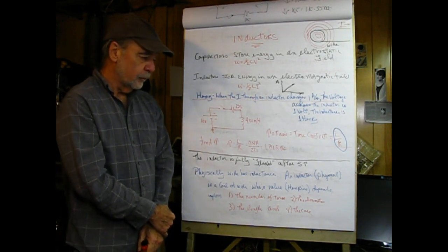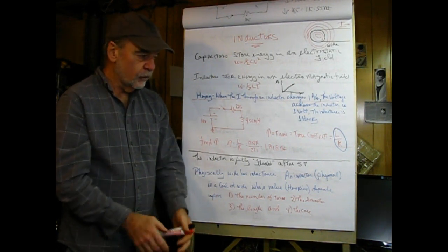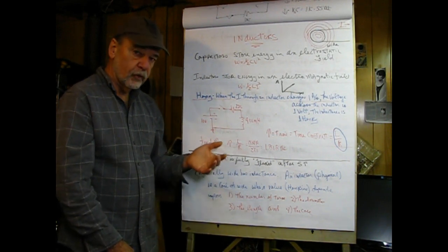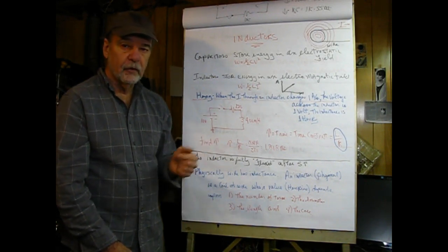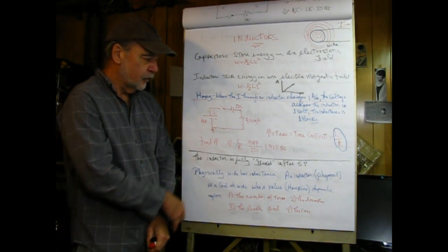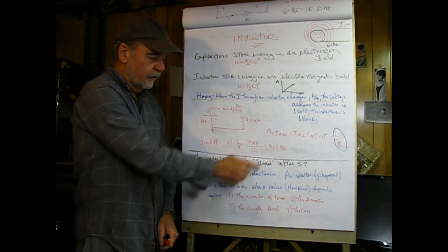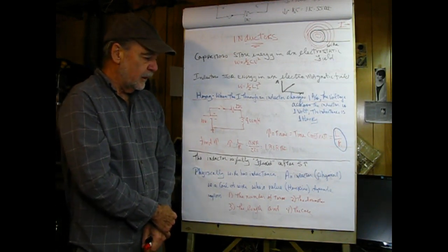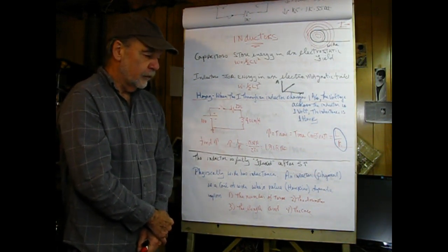Likewise, when we're charging an inductor, fluxing it, the rate at which that magnetic field grows is also equal to L over R. So all of the time constant material that we talked about before is applicable here, but as I said before, the inductor has characteristics which are opposite to that of a capacitor. Let's take an example. Find tau, where our circuit has a 220 ohm resistor and a 400 millihenry inductor. Using the math for the time constant, that comes out to be 1.818 milliseconds. What that means is when the switch closes, 1.8 milliseconds later, the inductor will be approximately 63% fluxed.